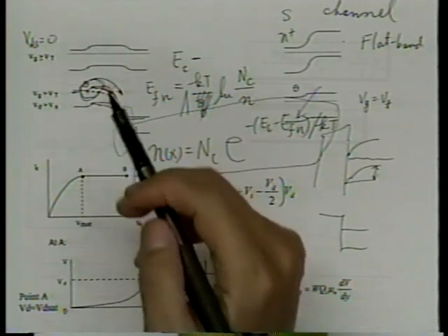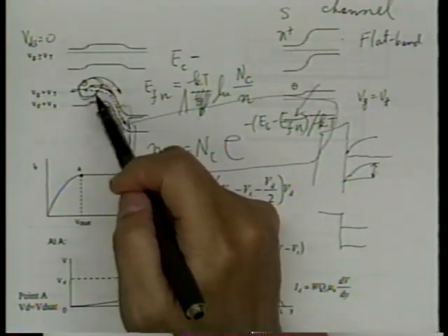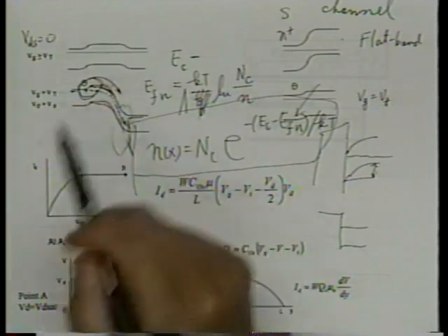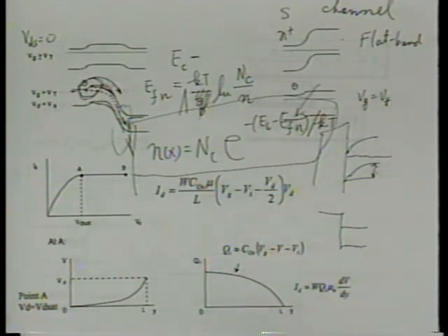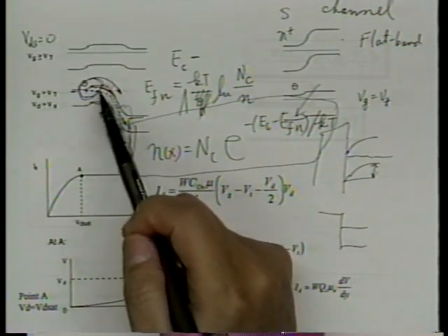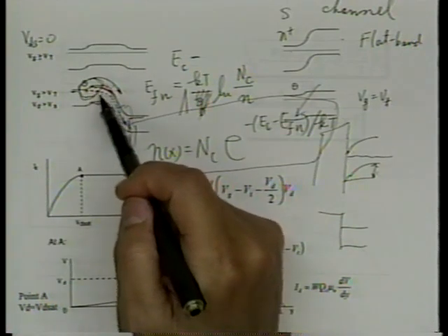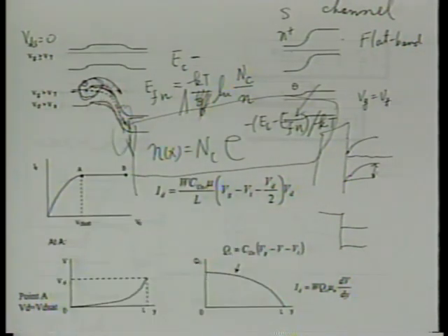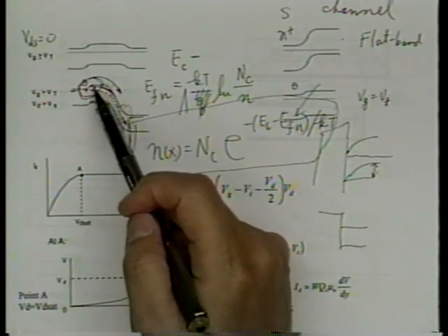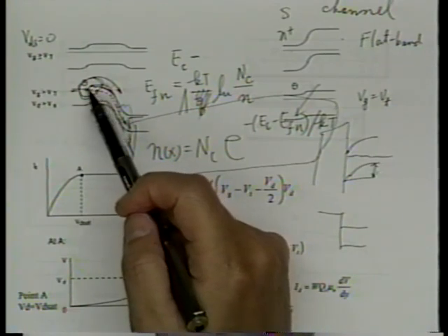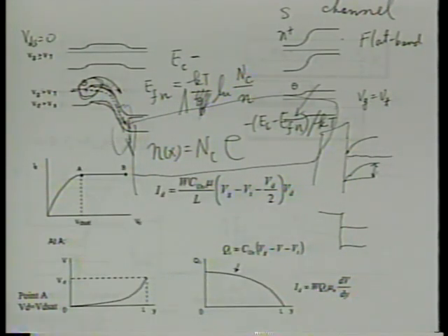That's a little useful because we actually know separately that the quasi-Fermi level should be more or less continuous, and cannot go through very large jumps. The quasi-Fermi level has to be pretty smooth because its gradient is proportional to current density. So if current density doesn't change a lot, then the quasi-Fermi level should not change very rapidly. So we know this is going to be smooth. Immediately, then we can tell there's going to be a small jump in the carrier concentration. Or put another way, if for some other reason you first know the carrier concentration, such as from the first few chapters, then from this you can tell there's actually a small energy barrier, for whatever subtle things it might do. You can tell that.